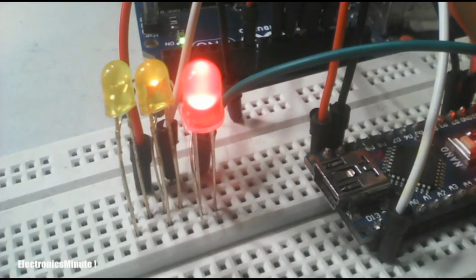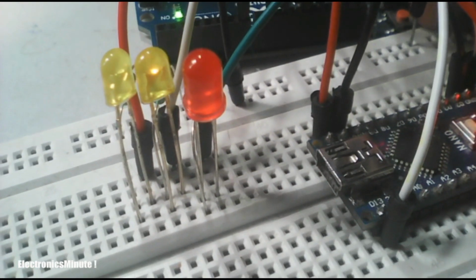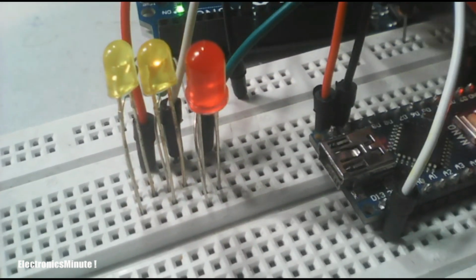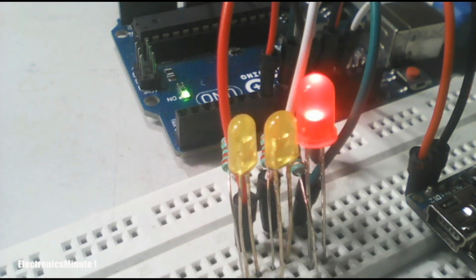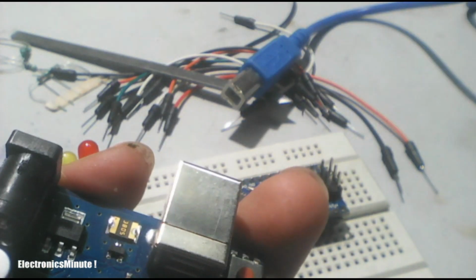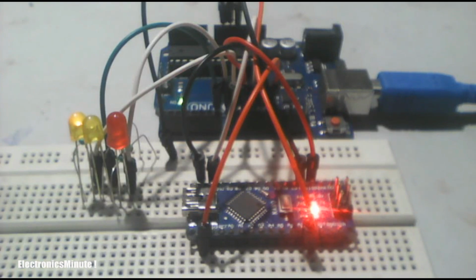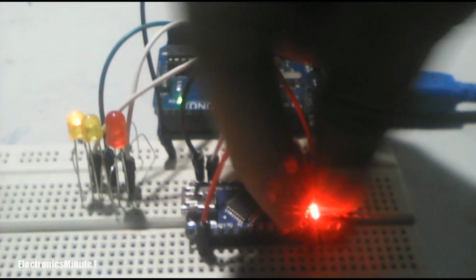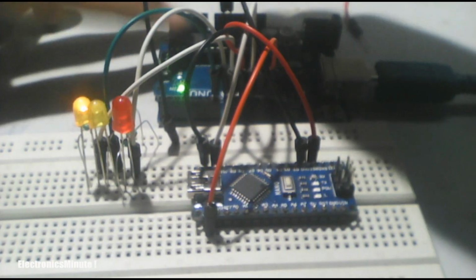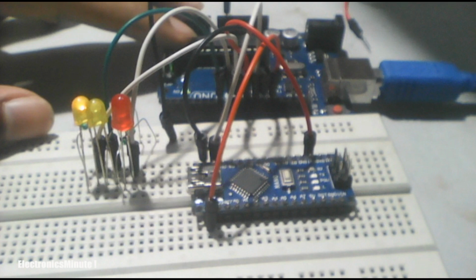If you get any error and the red LED lights up, try checking the connections of the two devices and take your time to select the board and programmer properly. This is very simple and the errors are due to only silly mistakes. There may be other situations, such as the USB port getting damaged or broken instead of the USB to serial converter not working, so that you can't upload a newly created sketch to the microcontroller. Then also you can upload the sketches to the Arduino boards in this way. So you have got a new option for uploading sketches to any of your Arduino boards.